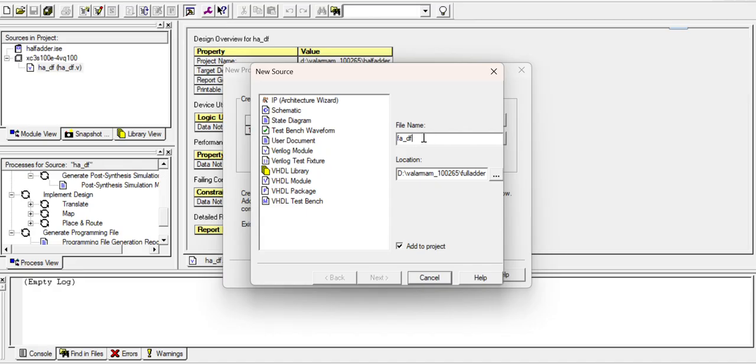It is better to give the same name for the file name and the module name inside the coding, to avoid confusion. Sometimes students give a different file name and a different module name, and while mapping into the structural design, the name gets confused. When you instantiate programs, you have to give only the module name.